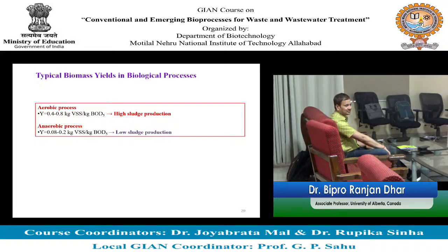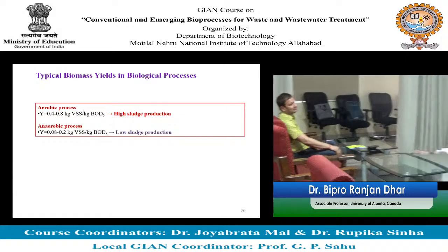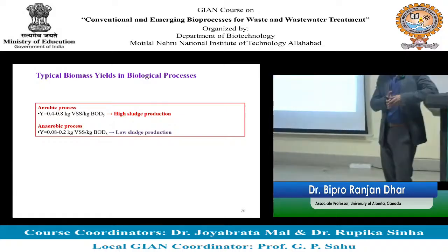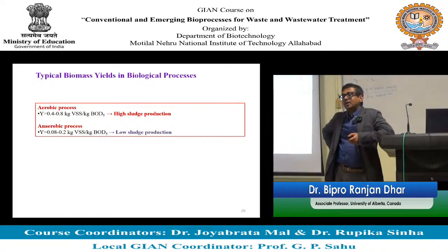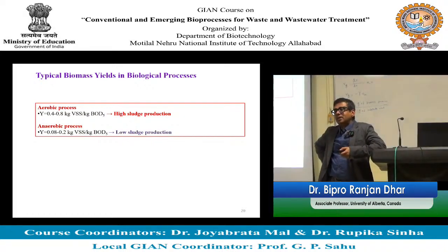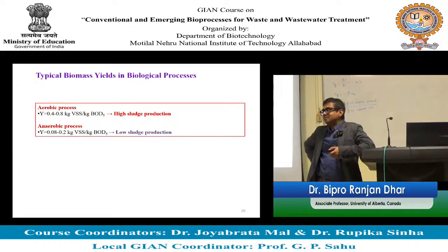So the question is, is that dye organic? Then how are you going to remove it using microbes? Probably you need to use chemical treatment, because if your dye is not organic in nature, bacteria are not going to use it. Everywhere you cannot apply biological treatment.